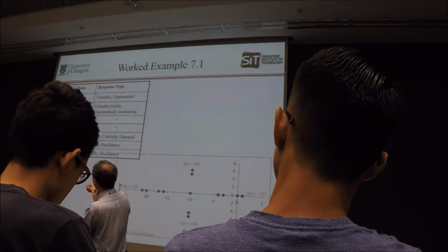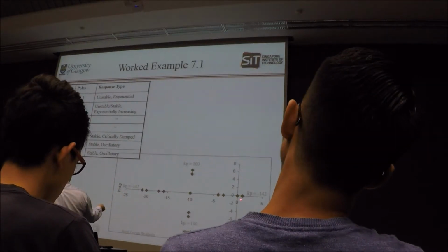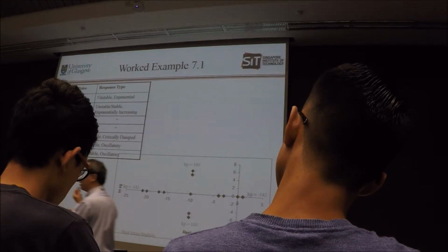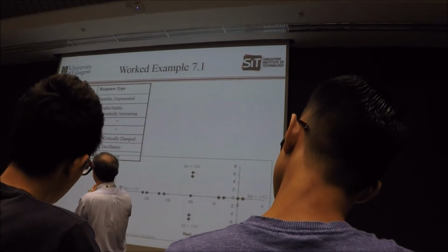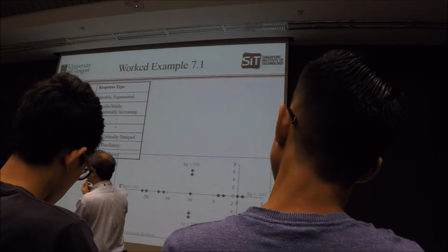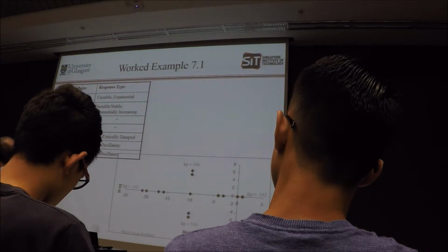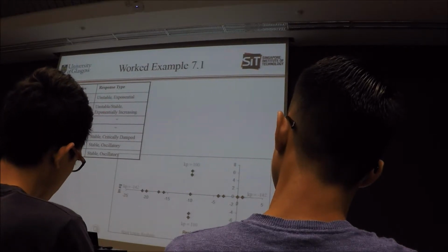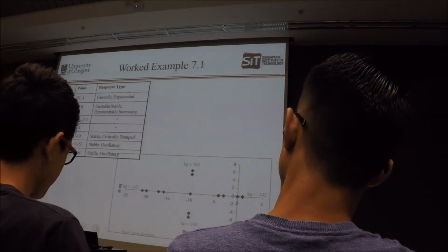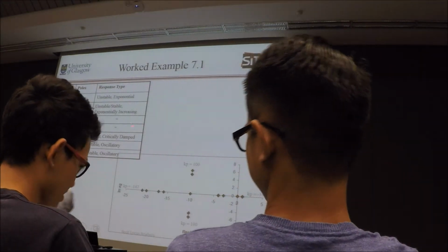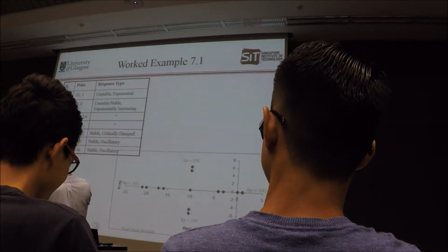When Kp is equal to minus 100, you have a pole at 0 and a pole at minus 20. So you have a marginally stable pole, because 0 is marginally stable, and minus 20 is stable. So you have one pole that is stable and one that is marginally stable. In this case, your response can actually be exponentially increasing depending upon what kind of input you put into the system. If it is unstable, then it's going to be exponentially increasing. So that is actually possible.